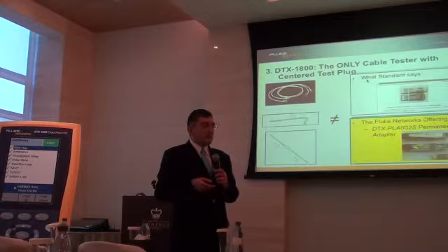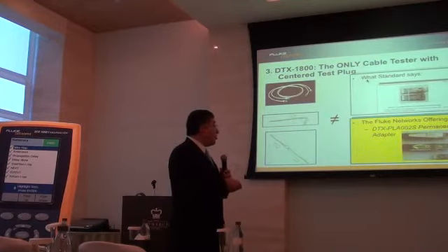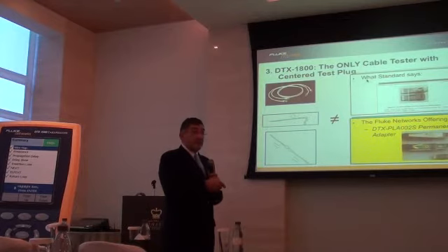But I'm saying that when you test with your Fluke patch cord, from one end to the other end, you check the performance of the cabling, right? Which patch cord? We don't have a patch cord. No, like these connectors, adapters. Yeah, adapters, right? So you check the performance of the link. Yes. So let it be X. Now, when you use the patch cord in a realistic world, patch cord to the equipment and patch cord to the user side, then the other patch cord is being used, not yours, which is not as good as this one. So the performance will be X minus Y, right?